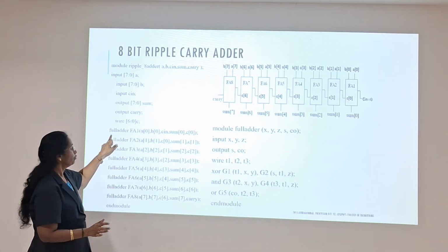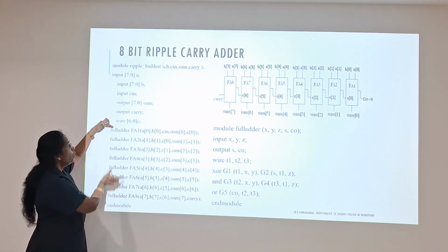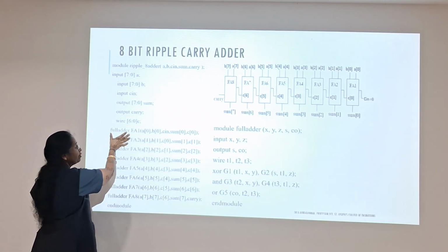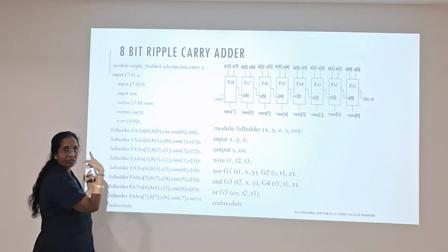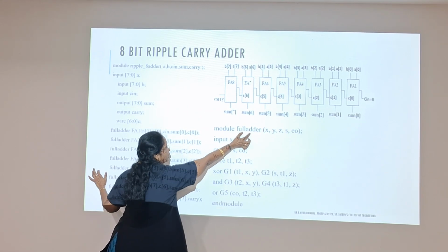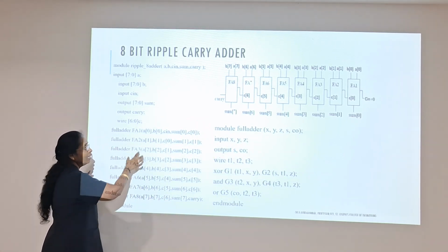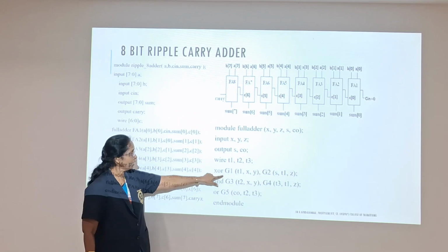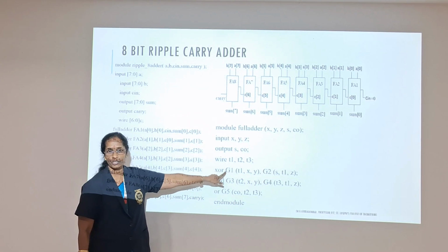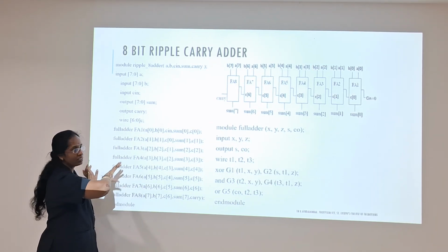Okay. Now, this process is known as an instantiation. What is the name I have used in the basic module full adder? The same name only we have to use here. If you change the name, then the program will not work. Whatever name you used, the same name has to be replicated here. And like our previous example, when we used the 2 XOR gates, we gave names G1, G2 like this. Similarly, here I am going to use this full adder totally 8 times.